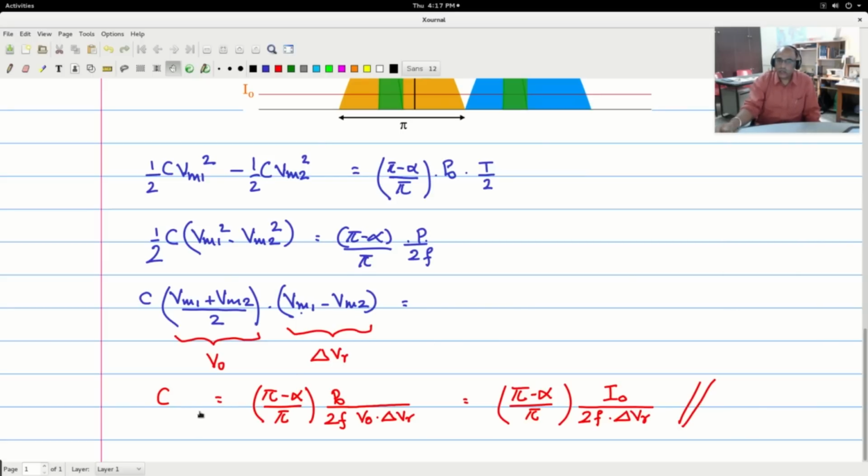Another very important criterion that you will have to take into account while you are putting the value of C in a real circuit is that when you buy an aluminum electrolytic capacitor, it has a very large tolerance, minus 40% to even 100%, those kinds of tolerances. So normally what you calculate, and then what you buy and actually measure, can have a very large and significant variation.